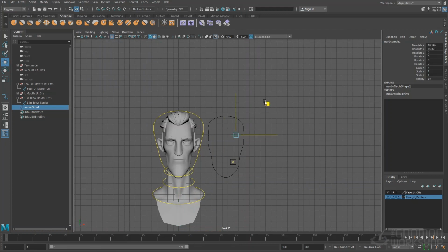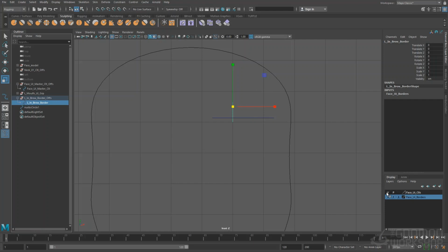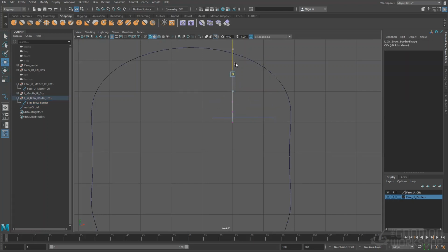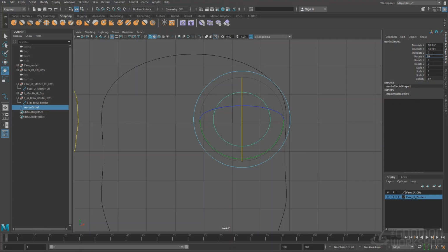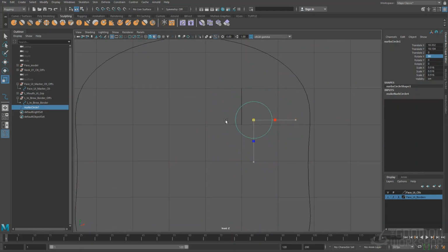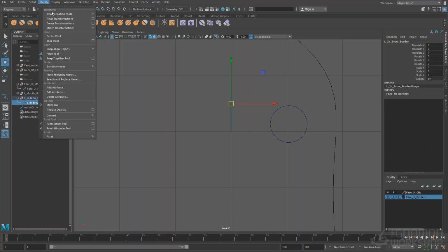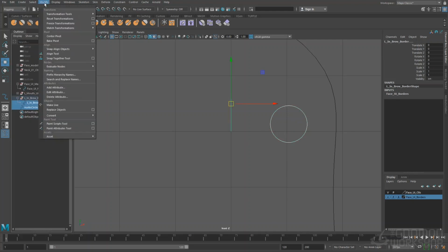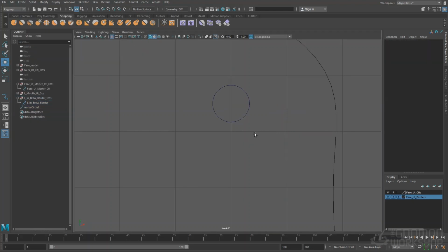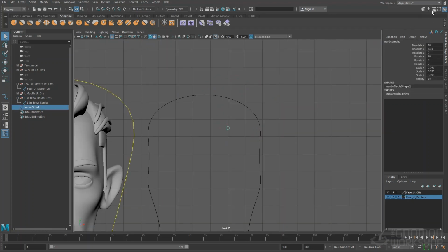We're going to do exactly the same. I can actually scale this if I want, like the control I mean. We can scale this more if you want more range on your control, but I'm gonna look for that later, not now. I'm gonna rotate 90 degrees this control just to have it this one here. And I also want to have the center of this curve, so I can actually just do a modify center pivot like that, and I can just do a match translation. And this is now at the center. I'm going to change the color of this shape.